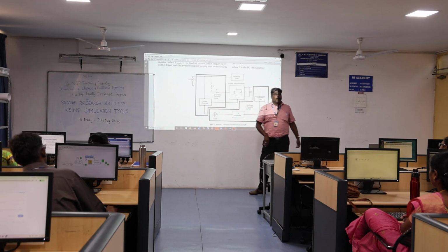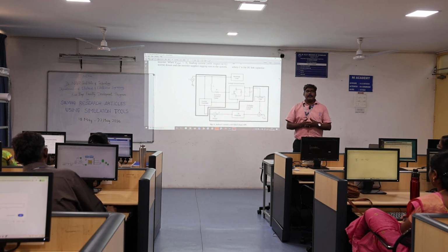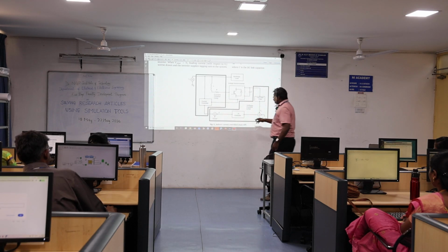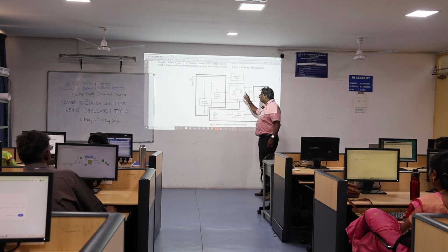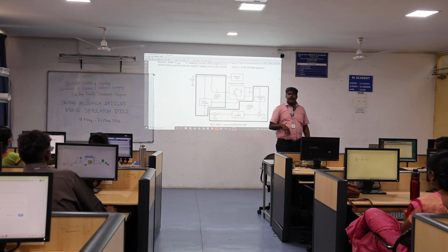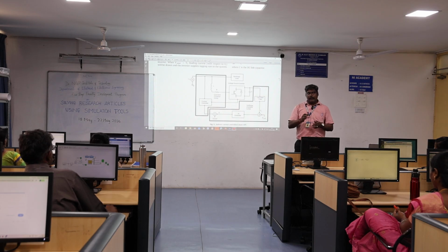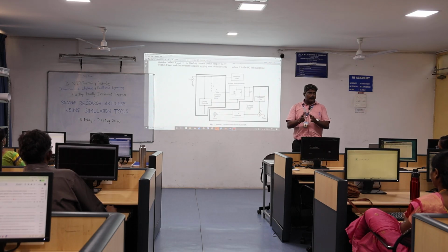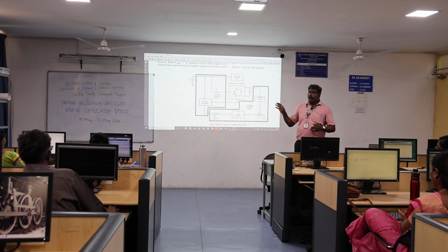But more than 30%, what will happen? Mostly the PI controller does not perform well beyond some percentage limit, maybe 30% or 40%. It will perform only for some percentage, maybe 20% to 30%. When you go for more than 30%, it won't perform.